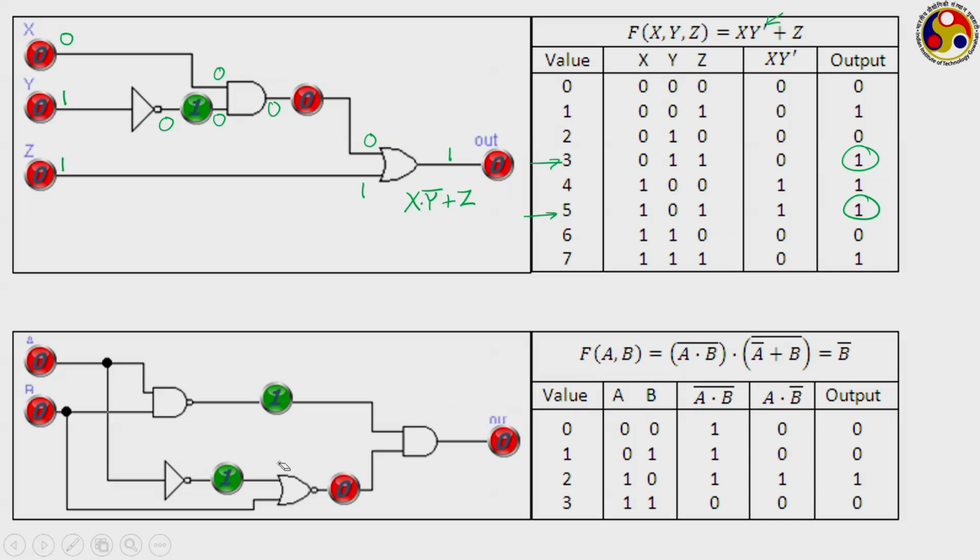One case is shown here, the truth table is also shown, but let us just try to see it properly. So, A and B both are coming to, let us give some names. Let us say this is number 1, this is number 2, this is number 3 and this is number 4. These are our gate numbers. So, after gate number 1, what are we going to see? A and B both go through a NAND operation. So, your output will be (A dot B) whole over bar.